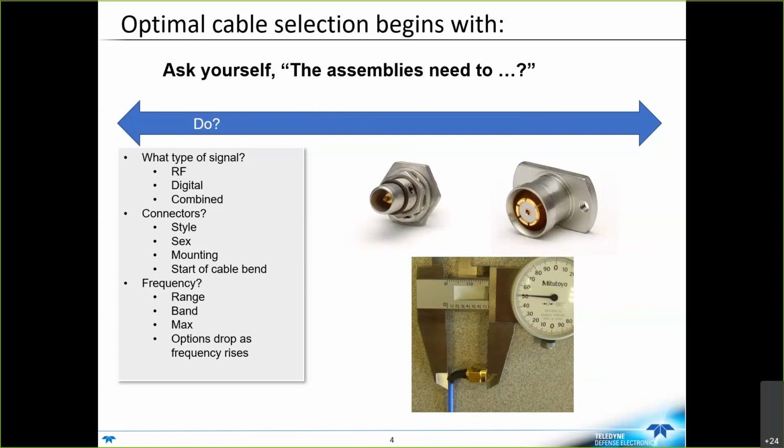So if you have a chance to think about that up front, have a little idea on the real estate where the cables are going to be, and if that height, as I have illustrated to you, is of concern, that's really valuable up front, because connectors, depending upon what cable they go on to, all have different mechanical lengths. And by the time we solder attach and we bend the cable, that height number can change fairly significantly.